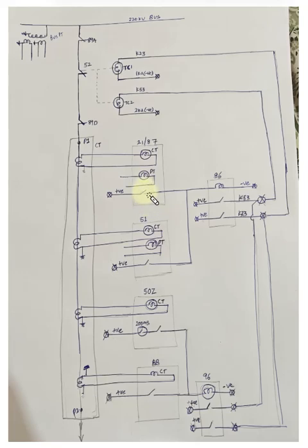when the impedance goes beyond the setting, then the relay operates, and this positive is being extended to the 86 relay. The negative is continuously given to one end of the operating coil of the 86 relay, that's the master trip relay, and when it receives a positive from the other end, the 86 relay operates, and the positive is continuously given to its output contacts, that is then extended to the tripping coil of the breaker. Okay, and then the breaker trips.